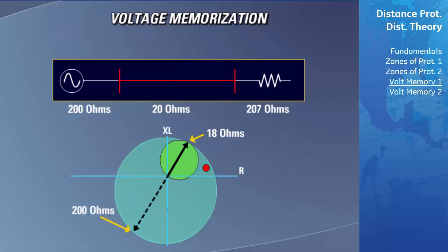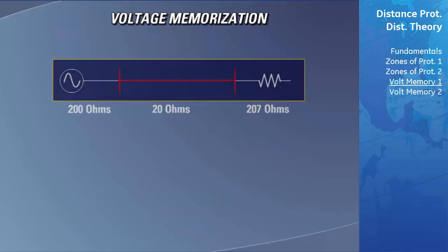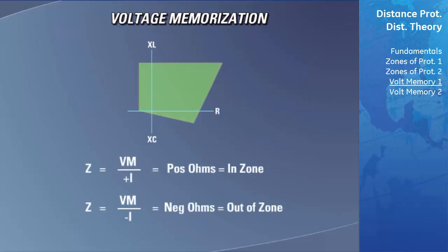Transients of this nature can occur in instances where the 3 poles of a breaker are opening or closing unevenly. If you are protecting a transmission line that is powered by a weak source, so that your system will have a very high system impedance ratio, this expansion Mho element should be disabled and a standard Mho characteristic should be used. Another alternative is to use the quadrilateral characteristic, where the shape and size of the zone of operation can be customized to fit your needs.